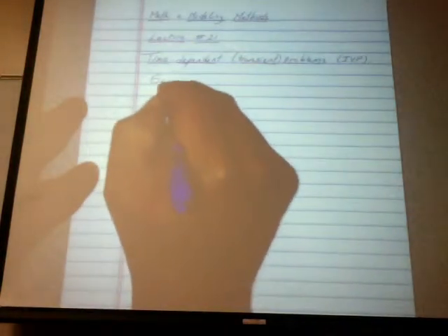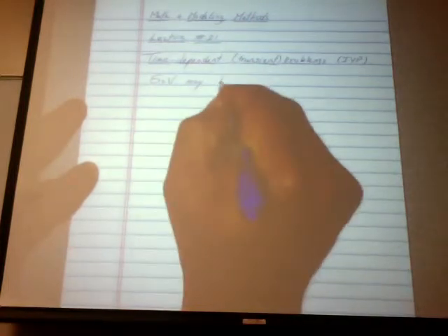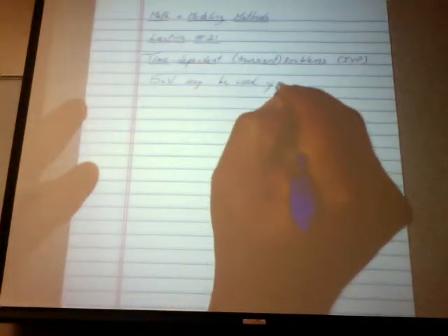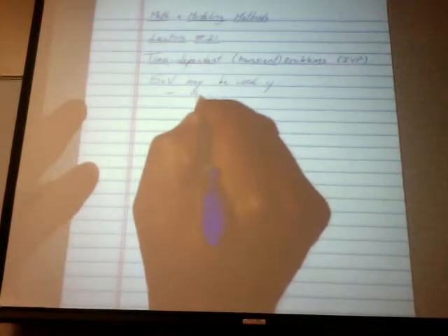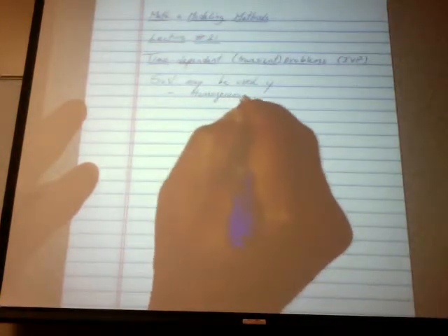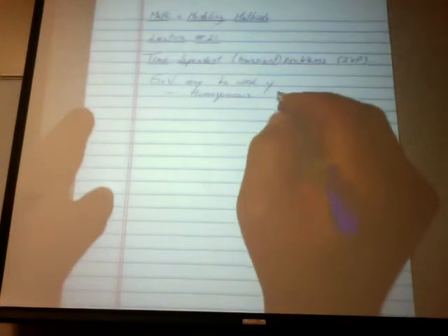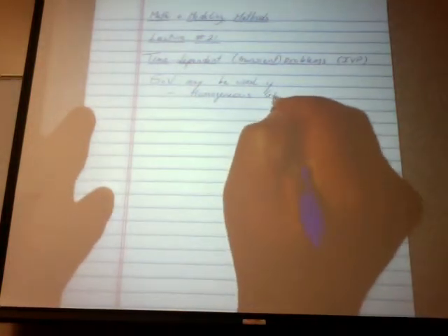So, separation of variables may be used if, and only if, all initial requirements apply. The problem needs to be linear. The problem needs to be framed in an orthogonal coordinate system, so it needs to be in a square, rectangle. Later, when we deal with cylindrical coordinate system, it has to be a cylinder or a hollow cylinder. We cannot escape that. So we have to have a homogeneous governing equation, essentially no generation or forcing of any kind